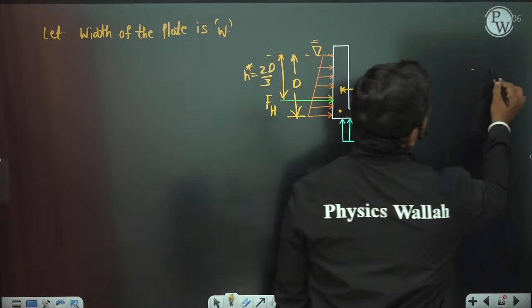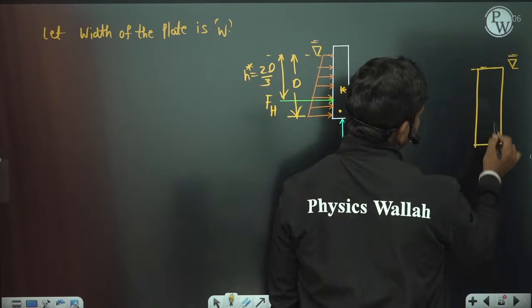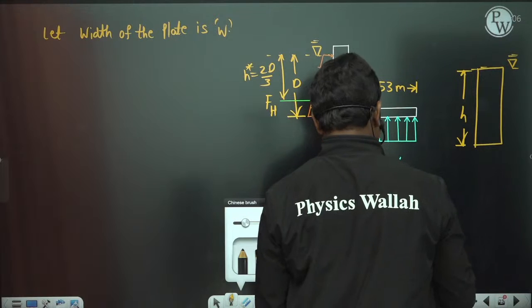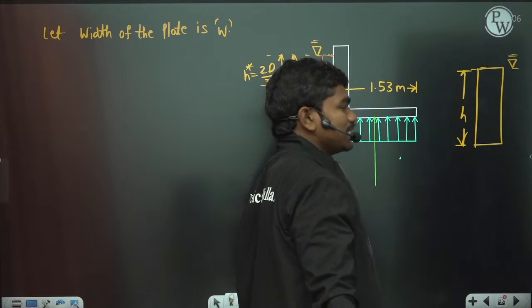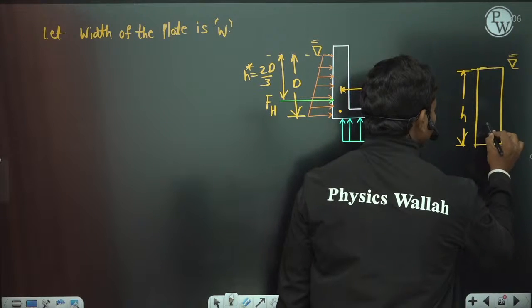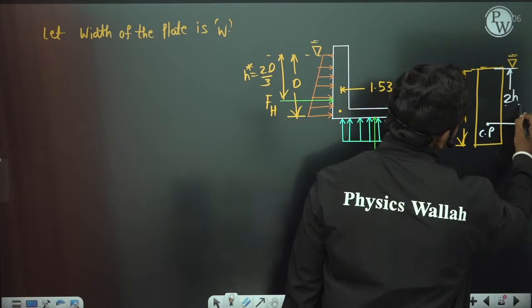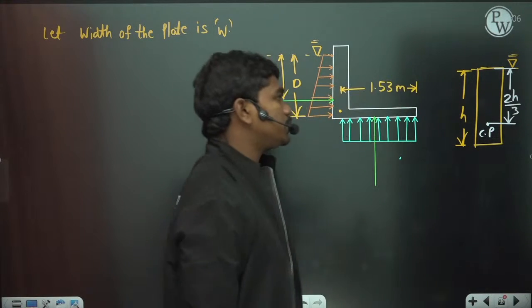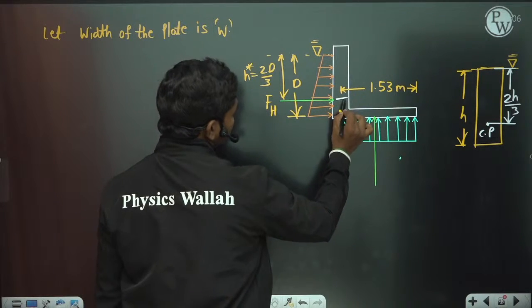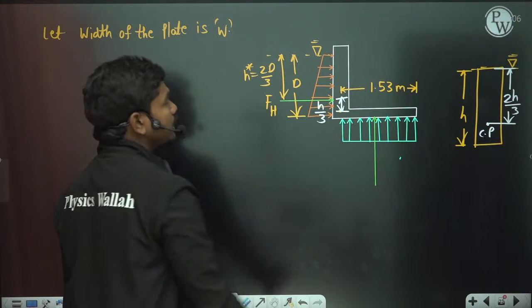If you remember, if you have a rectangular plate like this, and this dimension is h, then basically you might know this. Okay, I didn't teach you, I was teaching in the Prakam batch, sorry. But you might have known that if this is the center of pressure, Cp, then this value is 2h by 3, correct? But the rotation is about this hinge, okay? So what is this length? H by 3, okay? So this force is having a moment of F into h by 3.